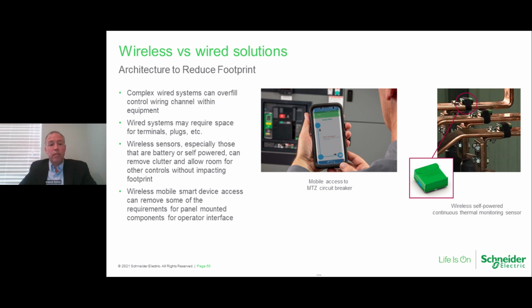But all those additional devices, integrating all of that equipment, for example, remote operability. If you have to hardwire a remote operability panel, that all takes space and adds complexity to the system. Newer equipment, our newer breakers and newer trip units, have the ability to access that device point to point so that it's secure, and we can use Bluetooth to access that device and move the operator away from the equipment when he's looking at it, without the additional wiring installed.